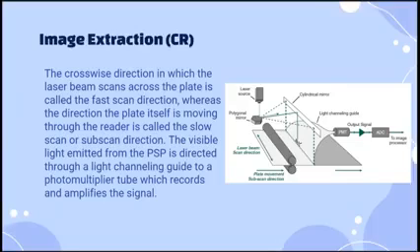Okay, the first step, in which the light is converted into an electrical signal, is performed by the photomultiplier tube, or the PMT, or the PM tube. The PM tube consists of a photocathode plate attached to an electronic amplifier. The photocathode is a layer of material which releases electrons when light strikes it through the photoelectric effect.